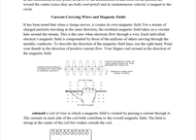As we said, there is a flow of current in a current carrying wire. We have seen how we can calculate the field strength in a current carrying wire. Now let us see how we can determine the direction of the field. As you see, if the current is moving up, our thumb must show the direction of the current, and the way our four fingers curl is the direction of what? The magnetic field. This one is the direction of the magnetic field.